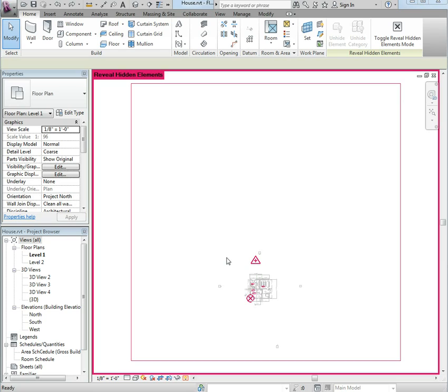You have two choices. You could either adjust the position of each and every named site's survey point. You could select everything on this page but the survey point and move it, or you can just pin the project marker to the page and move the entire project by 10 feet. Notice that when you do that, the coordinate annotations don't change.